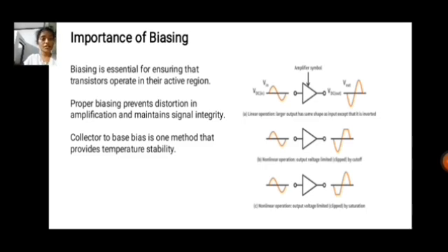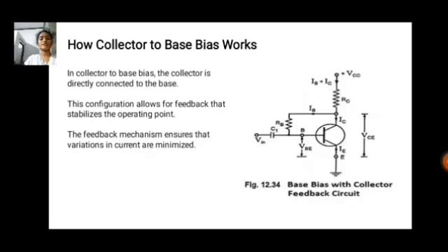Linear operation: the output has the same shape as the input except that it is inverted. Non-linear operation: output voltage limited by cutoff. Non-linear operation: output voltage limited by saturation.